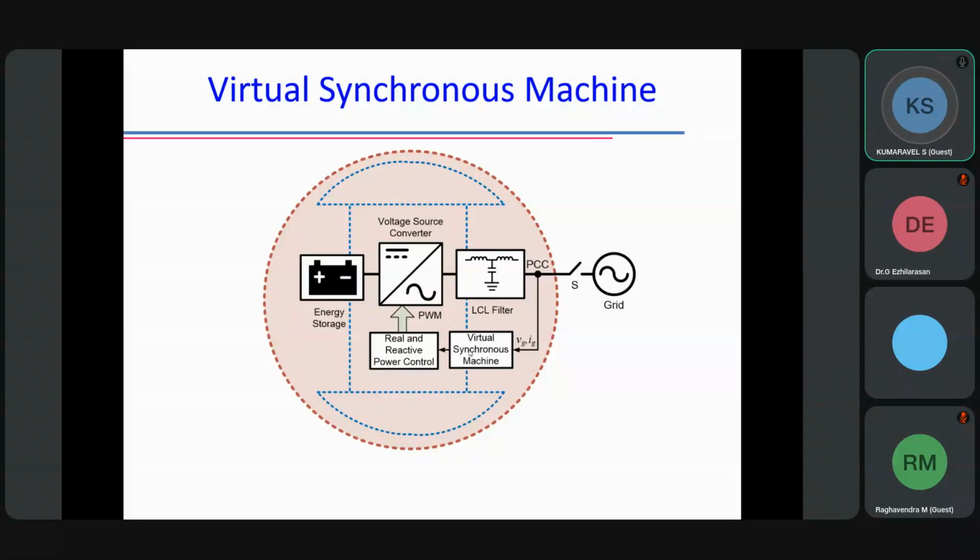If these parameters are satisfied, we synchronize the alternator, and we adjust the frequency by controlling the flywheel governor mechanism, AGC, that is automatic generation control. Then voltage we control using AVR, automatic voltage regulator. This is the usual control of a synchronous machine alternator.